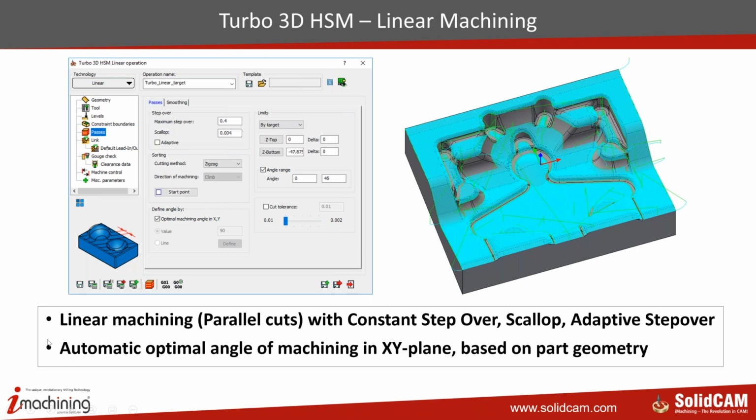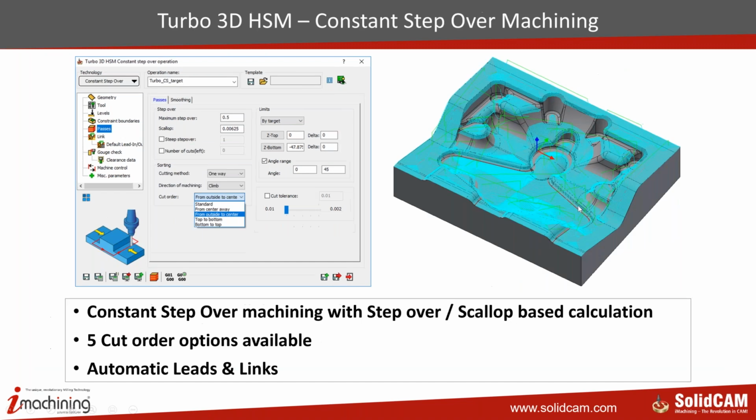And another very unique function which is available inside Turbo 3D HSM is a function called optimum machining angle in XY. So the moment you pick this function, Turbo HSM will take care of the most optimum angle to generate the toolpath in linear strategy. So we also have constant step over machining strategy inside Turbo 3D HSM.